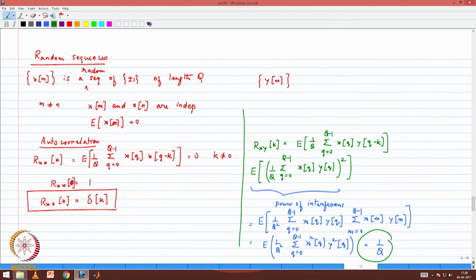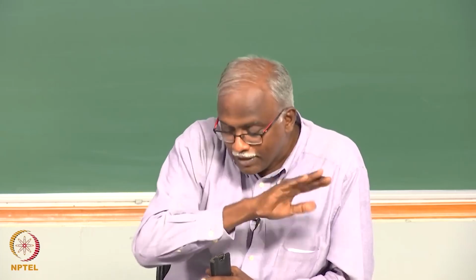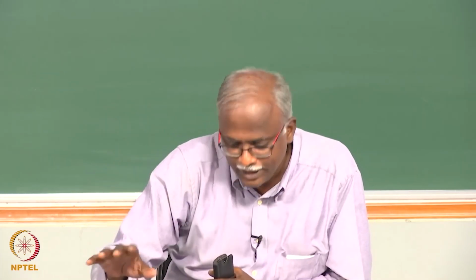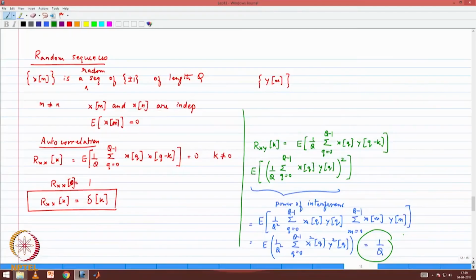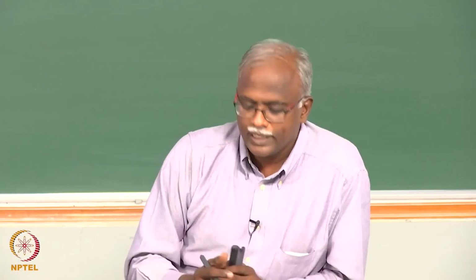And that's the fundamental property that we have taken from spread spectrum systems. Because if you remember, I told you about a tone jammer: if I have a sufficiently large spreading factor, it will suppress the interference by a factor of Q, so it will pretty much suppress the interference. You can see that this suppression is a very powerful one, and this is what we refer to as processing gain. Processing gain is what you get because of your spreading factor, and this is the reason why we do spread spectrum, not for AWGN, because in AWGN we will not get any benefit.